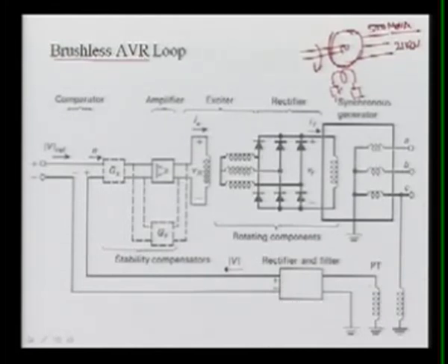Now, as I said, you will start from here. This is your synchronous generator, also called a synchronous alternator, or simply alternator. It is generating your three-phase supply, VA, VB and VC, and we have the armature winding here, A winding, B winding, and your neutral. We have just shown it as grounded. The armature is on your stator, as I said. Now your field winding is on the rotor.